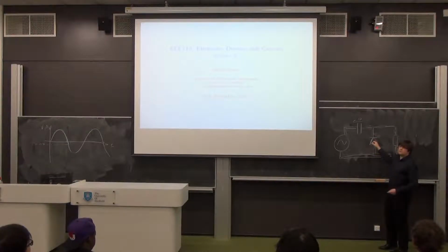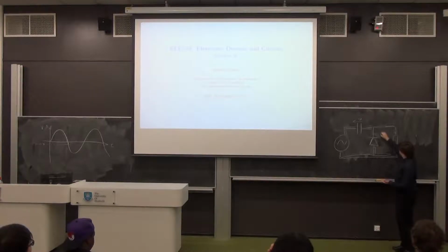So 0.7 volts across the diode, in the right direction, still no current flowing. So we've still got no voltage across the capacitor because there still hasn't been any charge put into it. But luckily we have 0.7 volts across there now. So this diode's about to conduct.